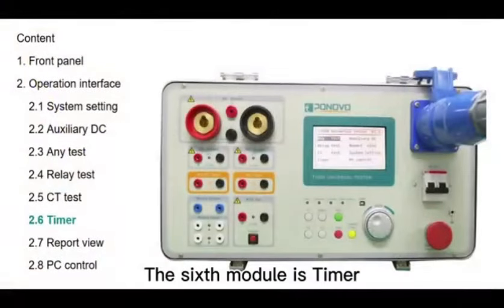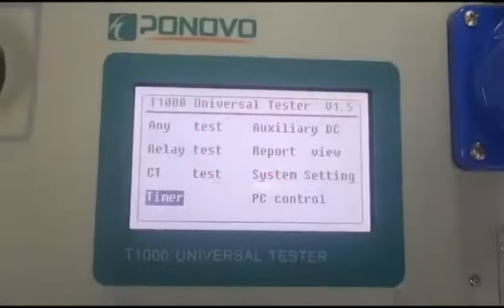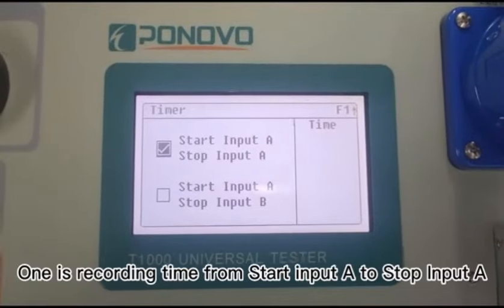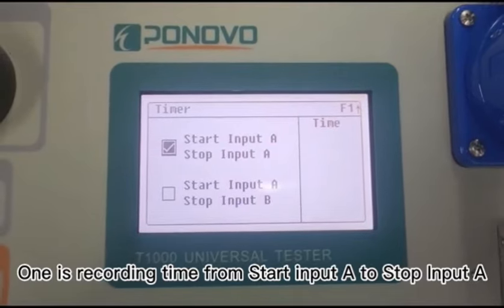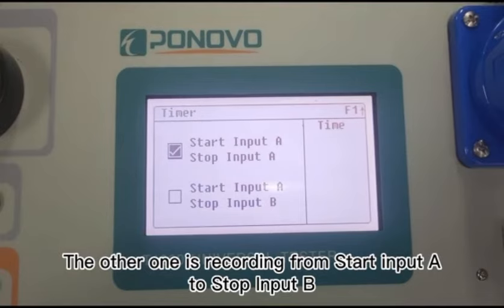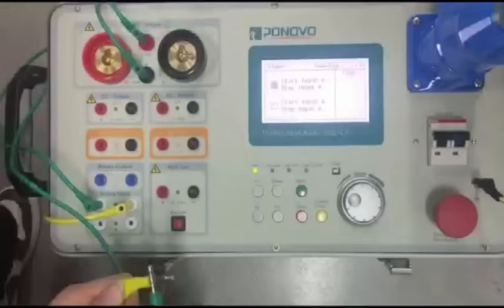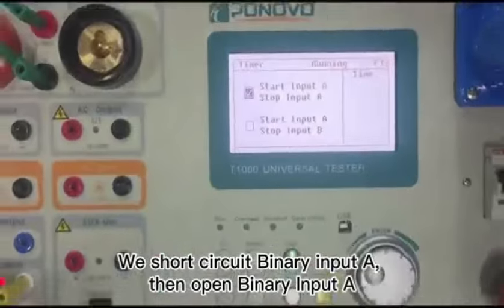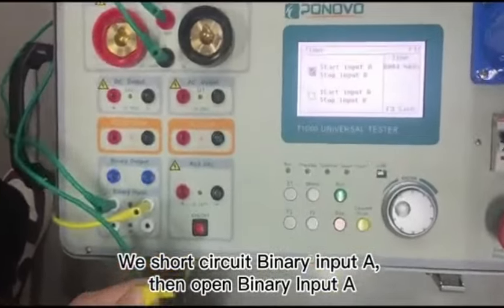The 6th module is timer. There are 2 test items. One is recording time from start input A to stop input A. The other one is recording from start input A to stop input B. We short circuit binary input A, then open binary input A. Here shows the time.